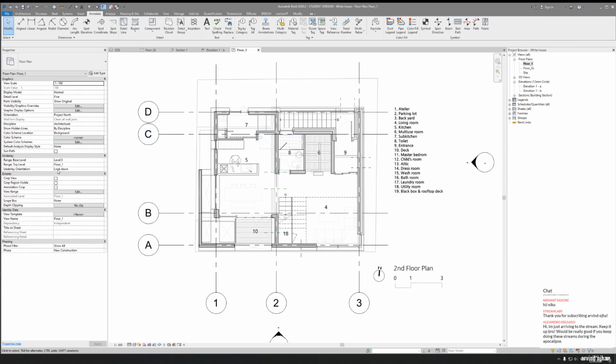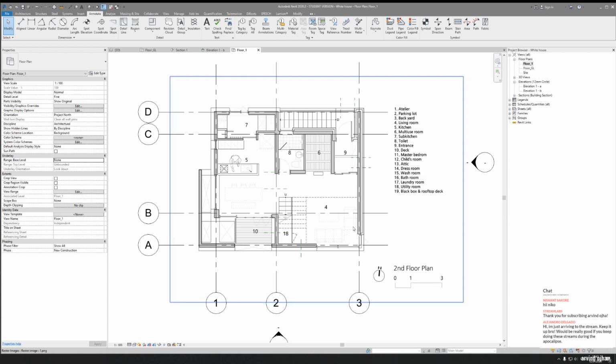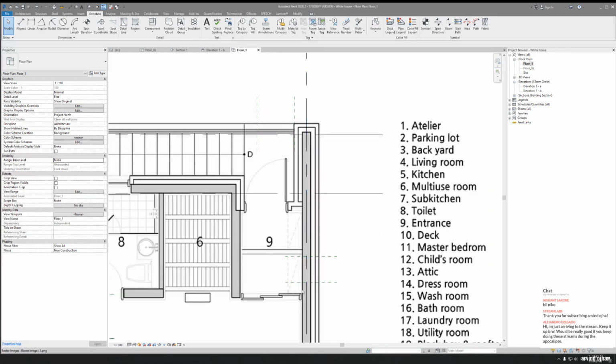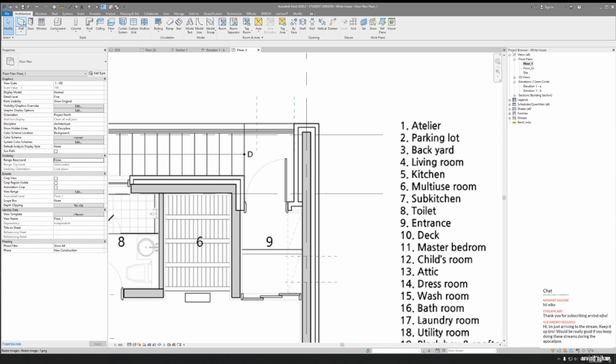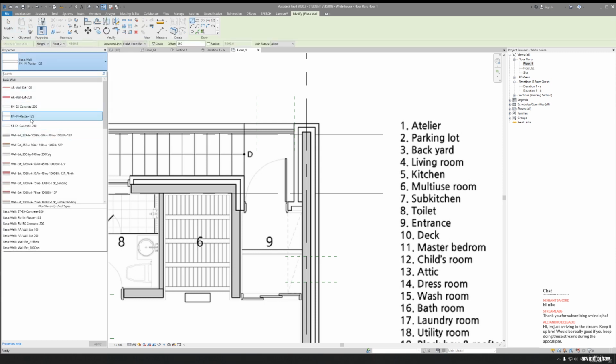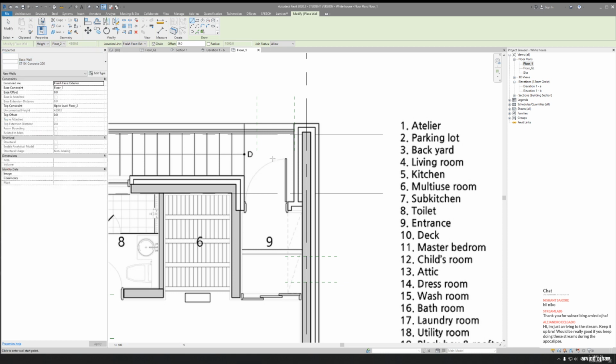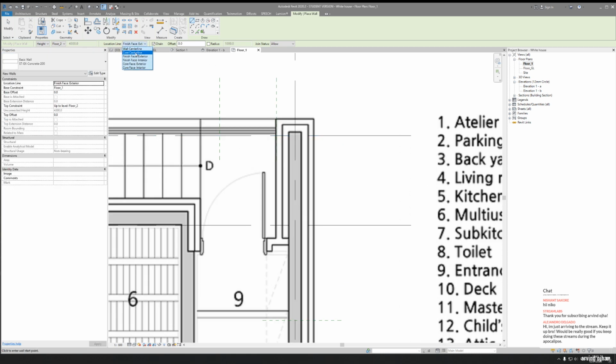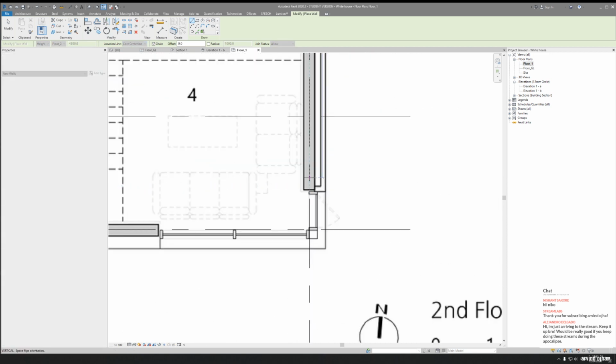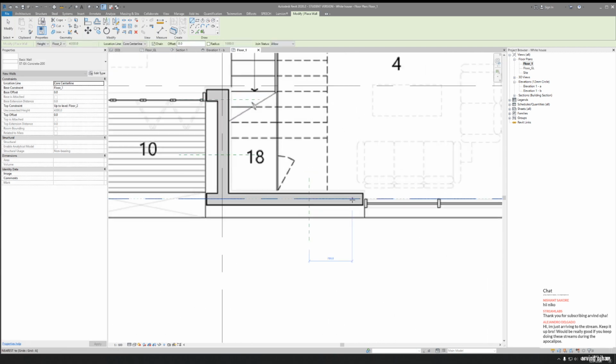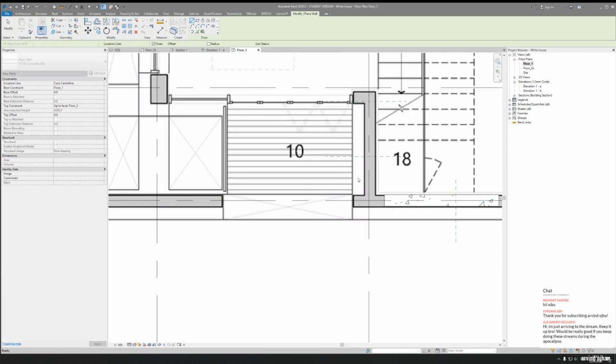Okay, so I don't wanna see the level which is on the base level, and I can see now only this level. And now we will just follow up what we did last time. So we're going to the wall, we find our wall, we need structure external concrete wall. We will change the connection to the core center line, and we will connect our wall to the center. Here we will do the same thing we did yesterday. So just continue working with that.